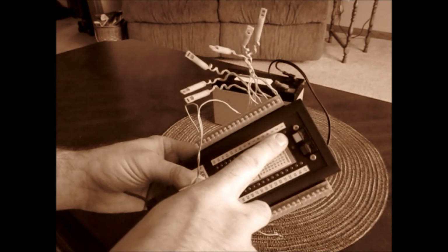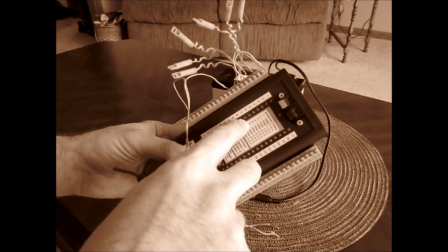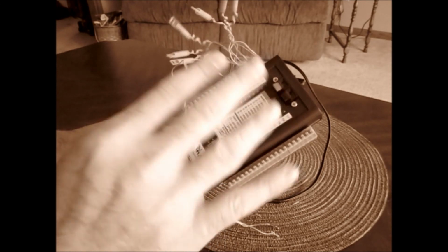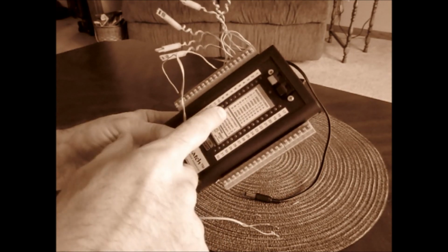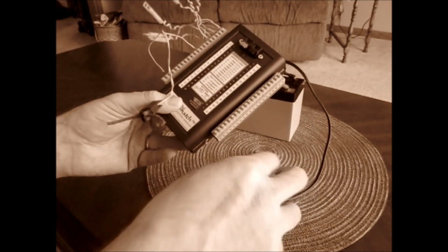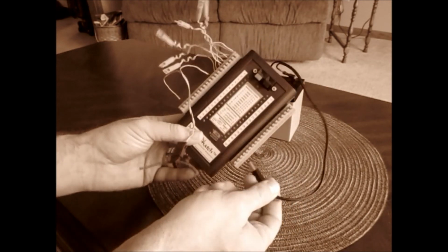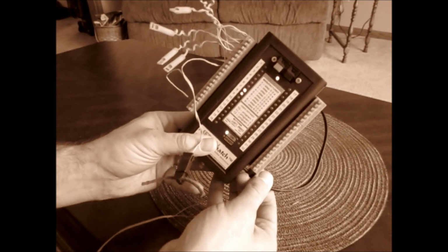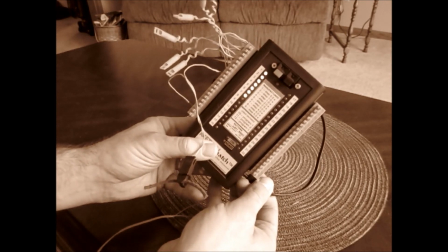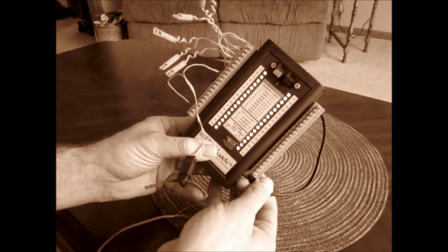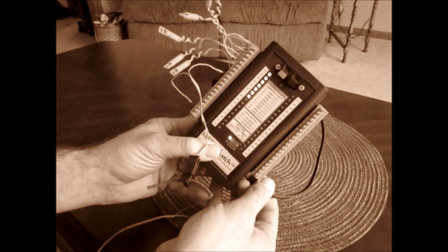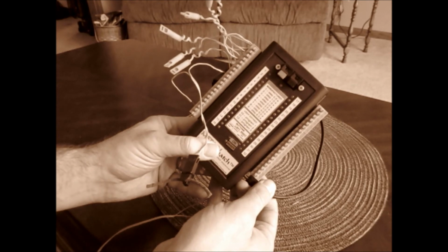So when you plug this thing in, what's going to end up happening is you'll see the continuity, and what we should see is lights 1 through 7 come on, and then 8 through 32 sort of flash, because there's nothing in 8 through 32, but 1 through 7 we should have good E-matches. So let's do a continuity test here. As soon as I plug it in, it automatically does it for us. Okay, so 7 looks like it's good, and 8 through 32 are flashing. So we are good to take this outside and give it a fire.